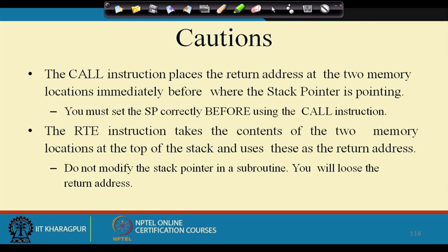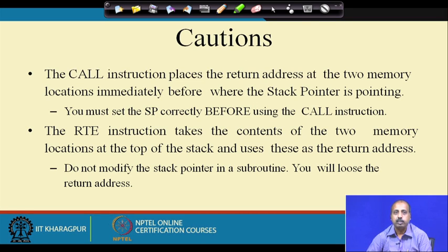On the other hand, the return instruction will take out the content of the 2 topmost memory locations. So, naturally, if you are not careful enough and modify the stack pointer register inside the subroutine, that may cause harm, because while returning from the subroutine, whatever the stack pointer value is, the processor will access the top 2 locations and put them onto the PC.